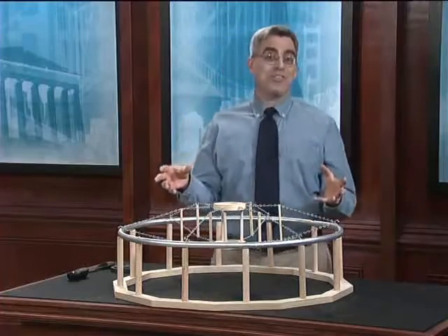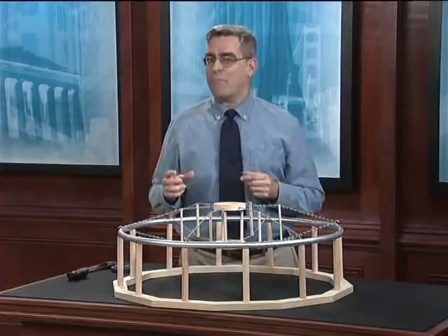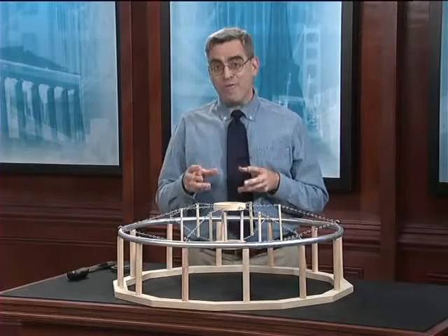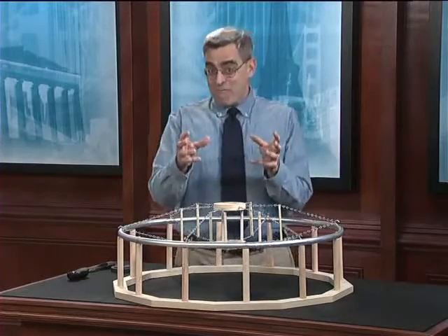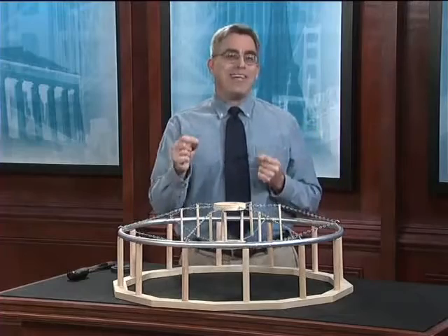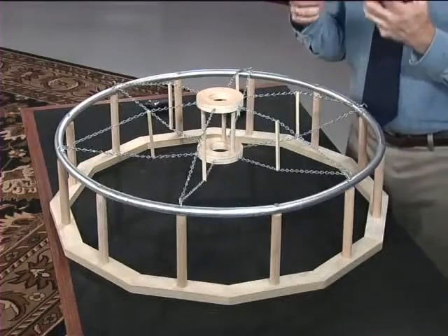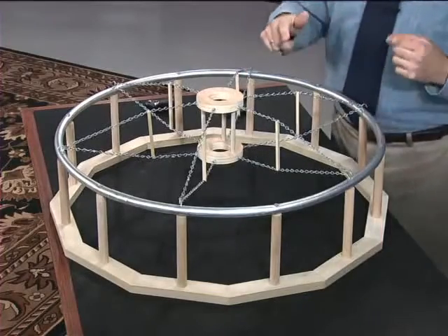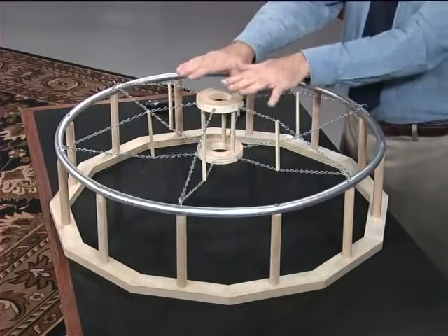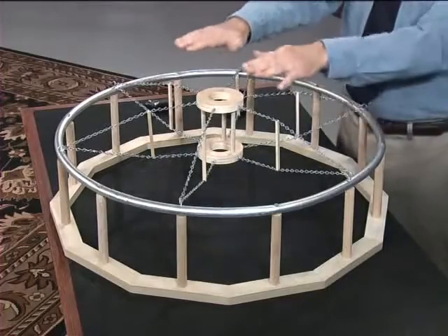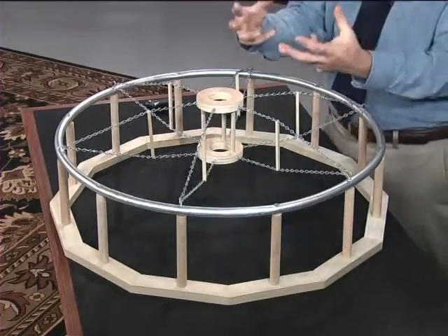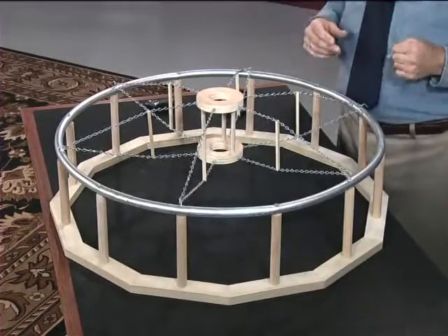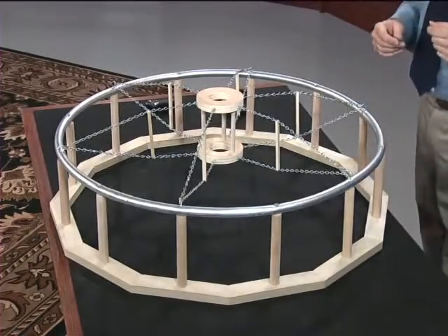That completes our structural system, or at least our simplified representation of the structural system of the Utica Auditorium roof. And what is it? Well, fundamentally, it's a giant bicycle wheel. In practice, it works just like a hanging dish, except through the addition of that second set of cables, we now have our roof positioned on top of the cables, sloping outward, so this roof drains normally without any sort of additions or drainage mechanisms that we had to have with our dish roof.